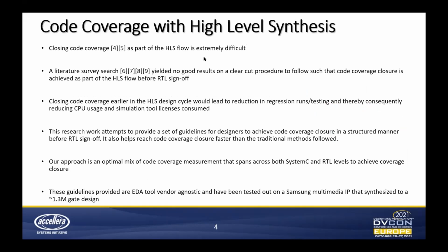This slide talks about code coverage in a typical high-level synthesis flow. Closing code coverage as part of the HLS flow is extremely difficult. A literature survey across many papers did not yield any good results on a clear-cut procedure to follow such that code coverage closure is achieved as part of the HLS flow before RTL sign-off.